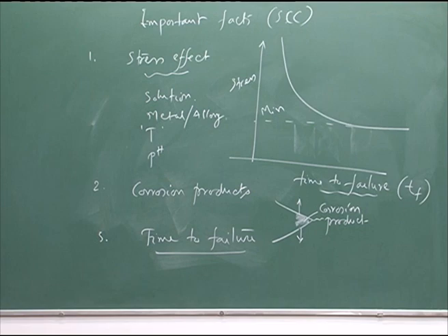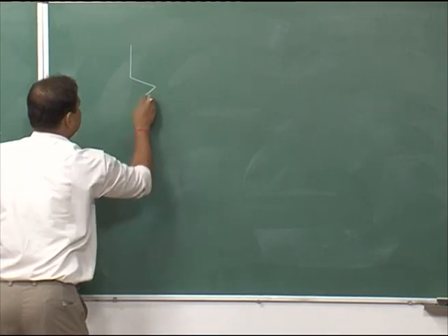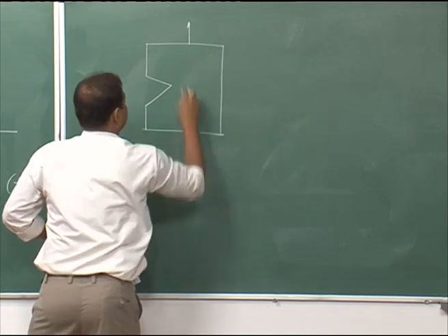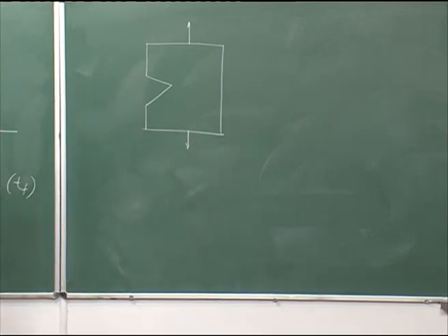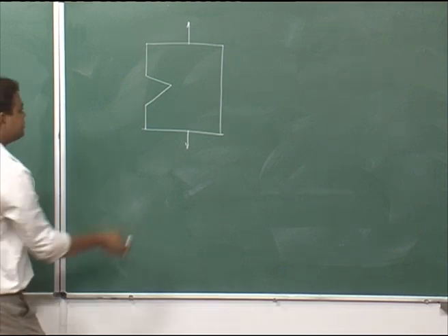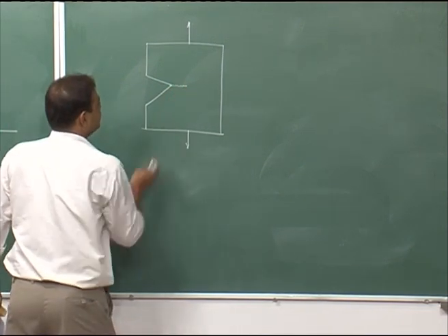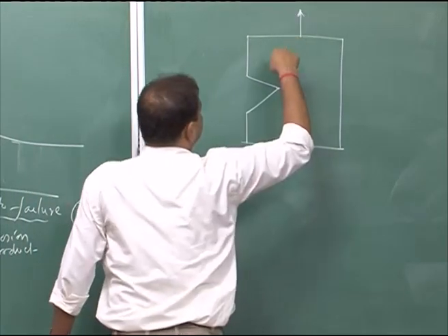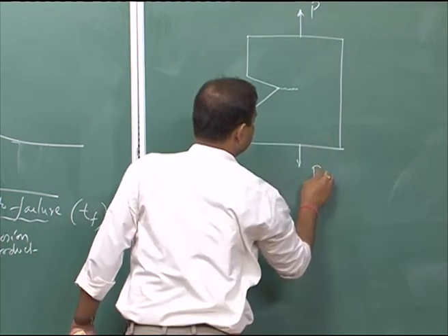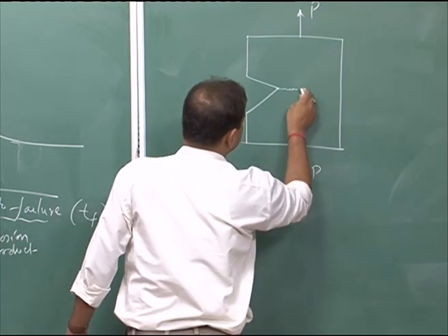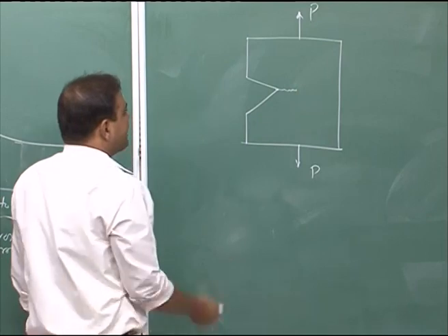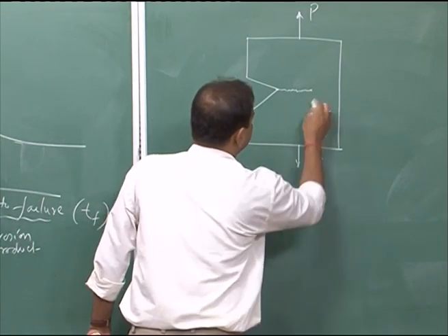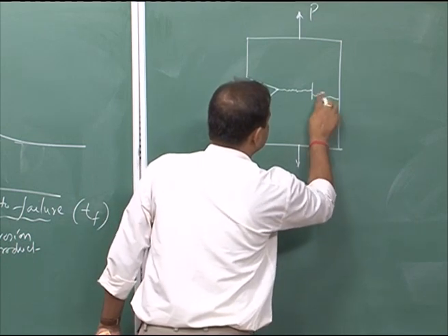now if you see this, let us say this is my crack tip and this is my total object. Now, we have this one under tension. Gradually the crack surface is growing inside the material, and if this is a constant load, gradually the remaining section has an increase in stress, and as it grows like this, finally you have a small ligament.